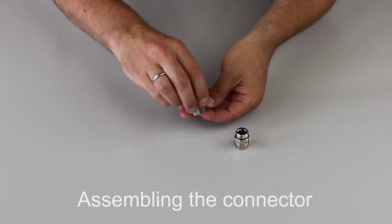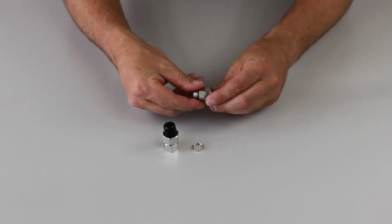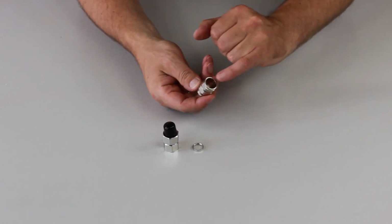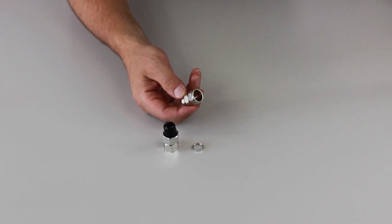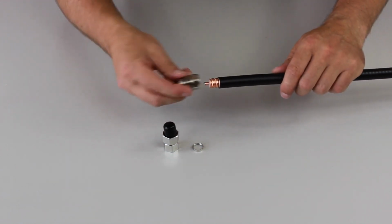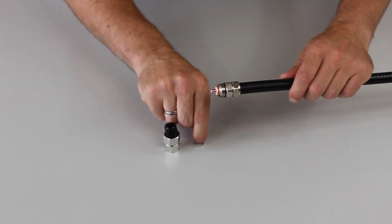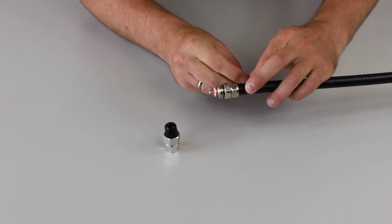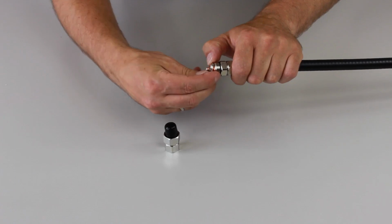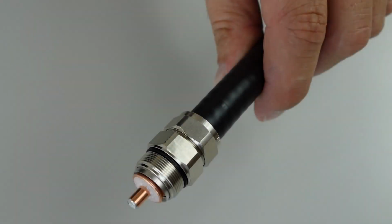Unscrew the connector. Make sure that you do not lose any parts. If necessary, slightly loosen the back of the connector so that the seal does not block the threading process. First, thread the back of the connector onto the cable and, if necessary, twist it slightly to prevent the seal from blocking. Push the back of the connector as far as it will go against the cable sheath. Then thread the slotted spring ring into the first trough of the cable.